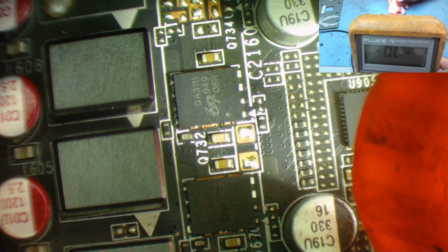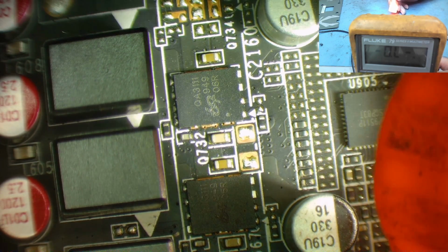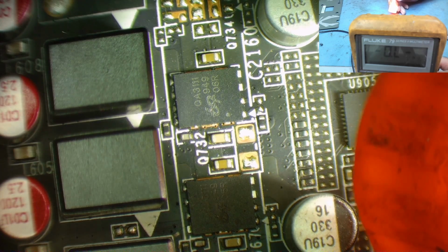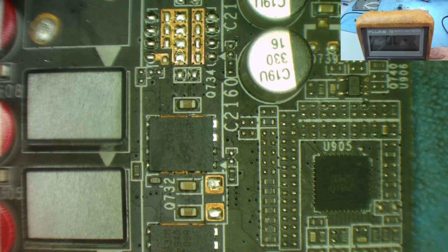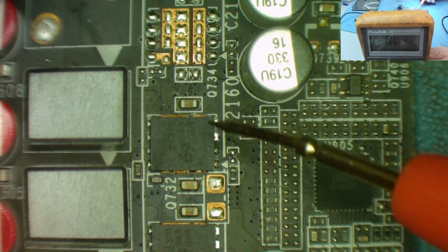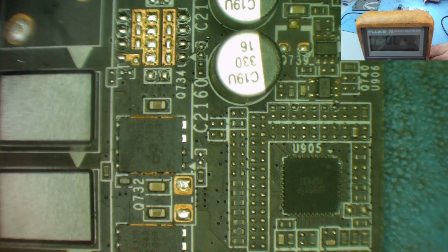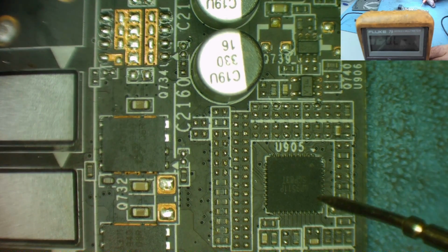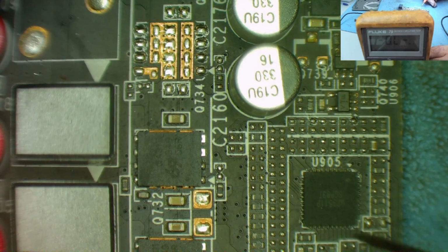They're not single MOSFETs because there's one by each coil. So they're at least dual MOSFETs. Let's have a look to see if we can find the datasheet for these. I couldn't find a datasheet for the QA3111, but I can buy them. But I did find a datasheet for the UP9511, and that tells me all I need to know about these. So let's have a look at this datasheet.